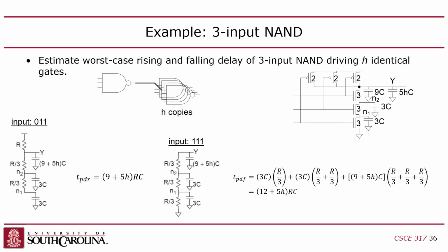Now you can imagine, by the way, in real chips, you're never going to see a single gate with more than 4 or so inputs, right? This is the problem: you get hammered once you start putting all these transistors in series. You know what I mean? So you're not going to see a 20-input AND gate or NAND gate. The cell libraries you get from your fab are always going to have relatively few inputs. If you need more inputs, you just chain together multiple gates to create a bigger logic circuit. You guys with me? Right?